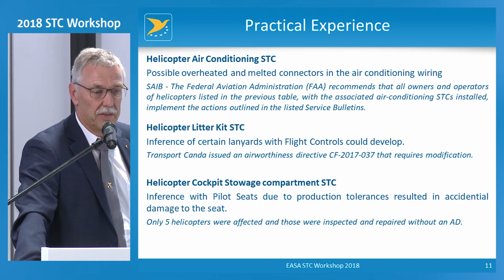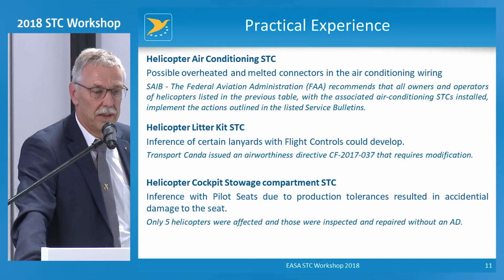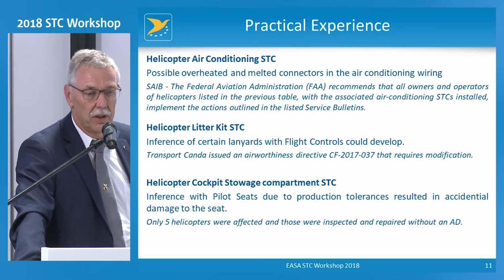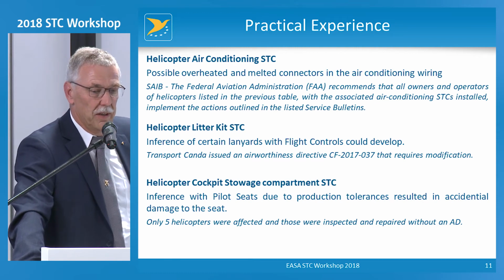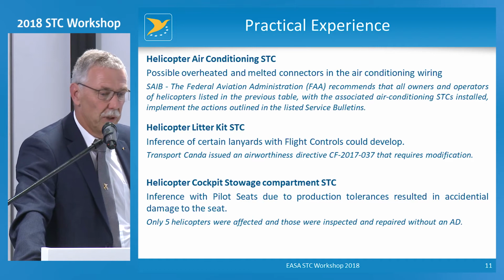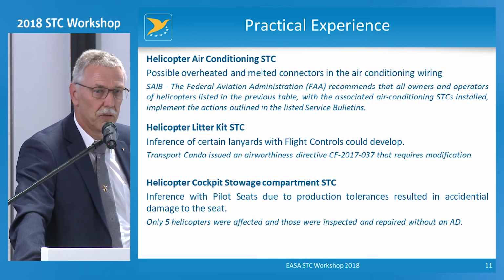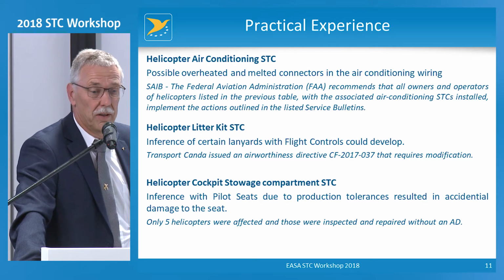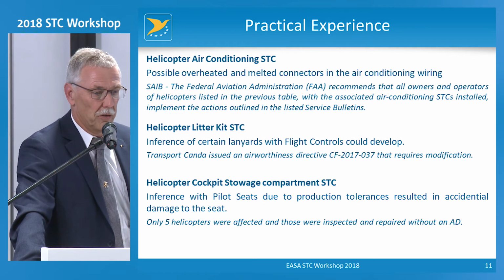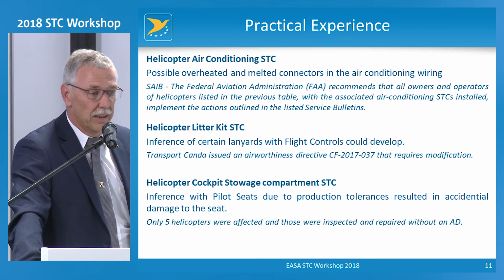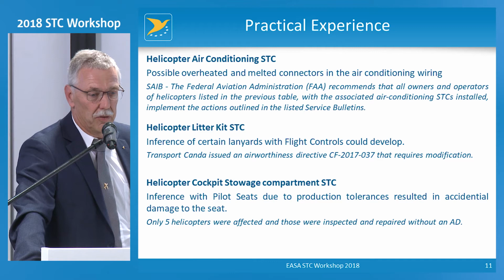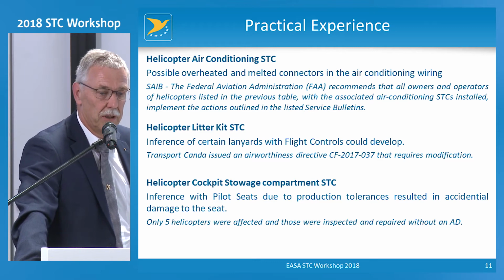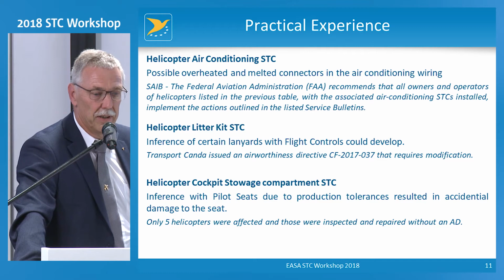Another item that has resulted in a Canadian AD is stretcher installation, where on one side of the helicopter you install a stretcher instead of the seat. And it was installed in a way that some of the parts could interfere with the flight controls. And this was not seen in the initial installation, or it was probably also avoided during the compliance finding and the inspections. But obviously it could develop in service, and therefore there has been an AD to prevent that.